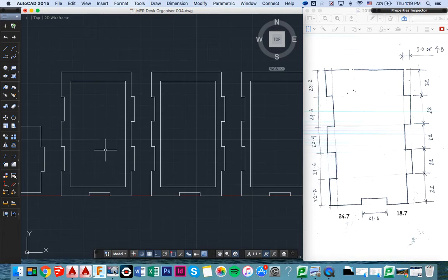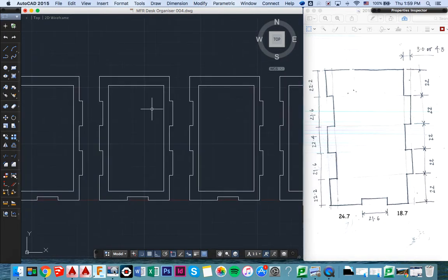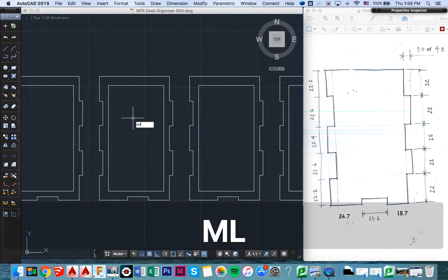Just leave that first one, we won't draw on that, we'll keep that as our master. Methods to draw a design or a pattern on your sides. The first one we're going to go with is the zigzag, like the example that I showed you earlier. So for that we need to use the command multi-line, which is ml, mline.